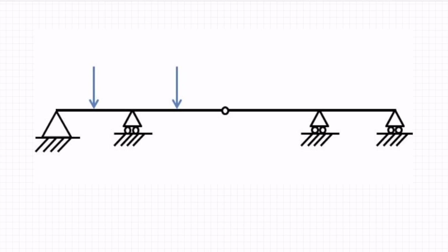Following on from that last question, we've got a slightly more complex beam now, and we have this pin in the center of the beam, and we've also got roller reactions. And now, unlike the last time round, because we have two rollers, we cannot just assume that the vertical reaction is going to be 0 on both of them, because you can easily get resolved moments here and have a vertical reaction going up on one and down on the other, or up on that one and down here. So we cannot assume that these are going to be automatically 0 vertical.